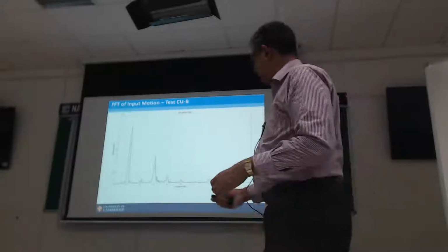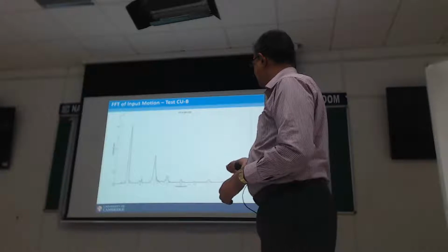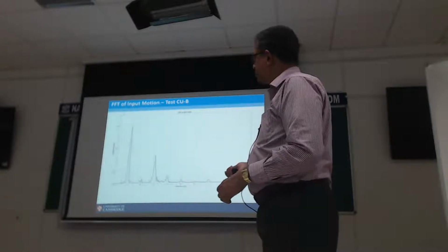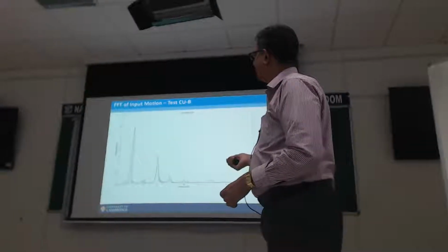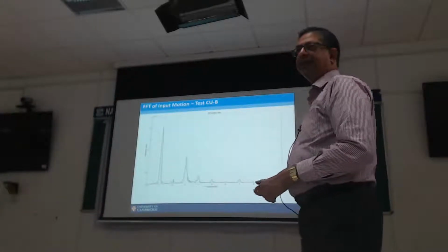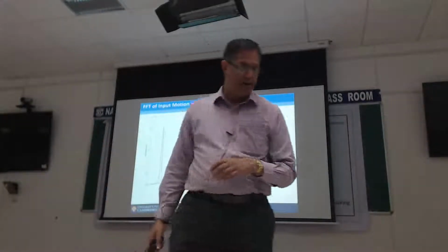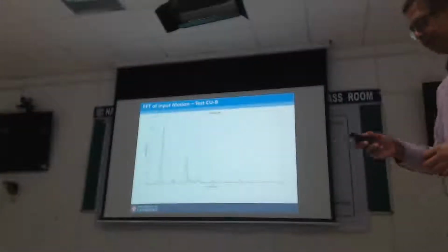We also looked at the frequency response of the input motion. So most of our energy should be at 1 hertz at prototype scale, and we have a component at 3 hertz. Most of these shakers have a 3 hertz component. That's just the mechanical resonance in the system.